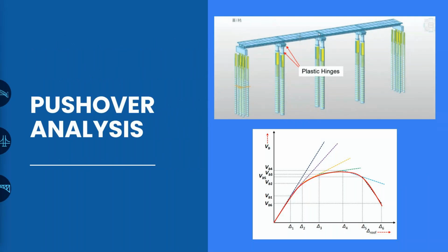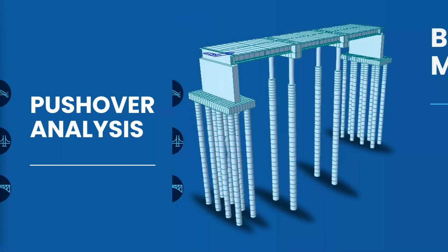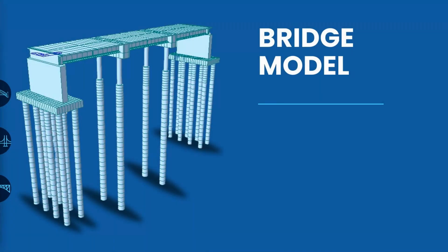So the type of pushover analysis that we will be carrying out in our structure will be with respect to the uniform acceleration method, or if the structure is symmetrical, then in that case we can also go for the loading pattern in case of the fundamental mode of that particular structure. So let us go to our bridge model that we were discussing earlier.